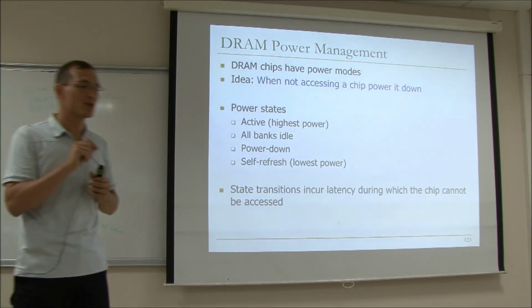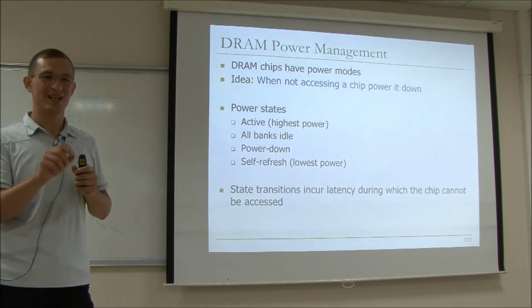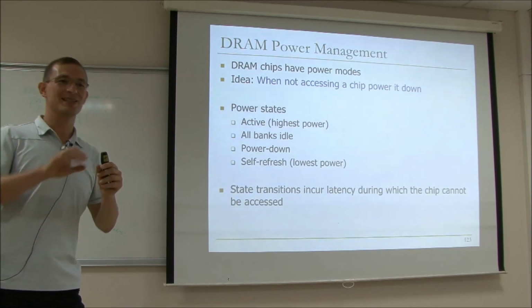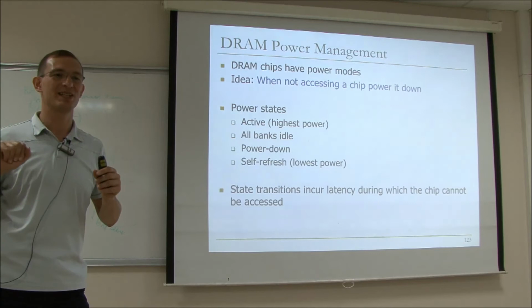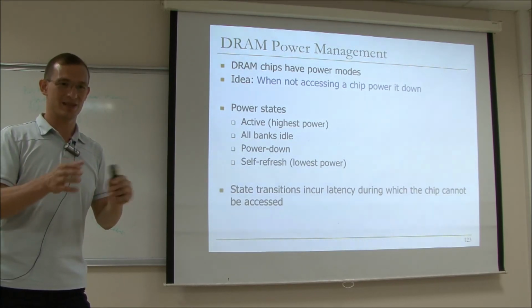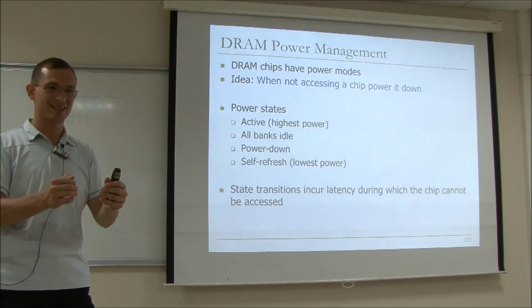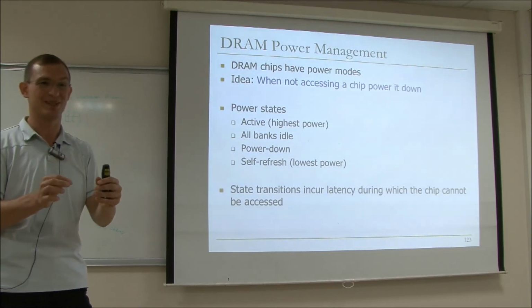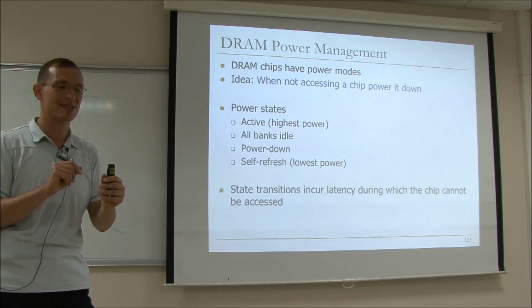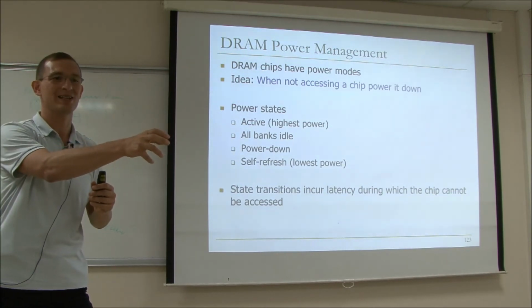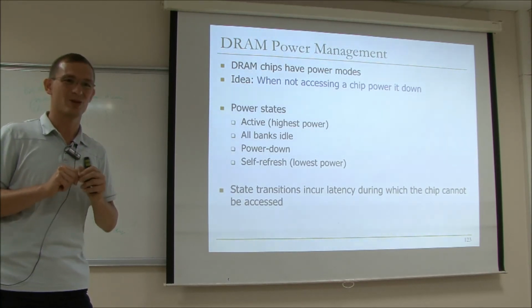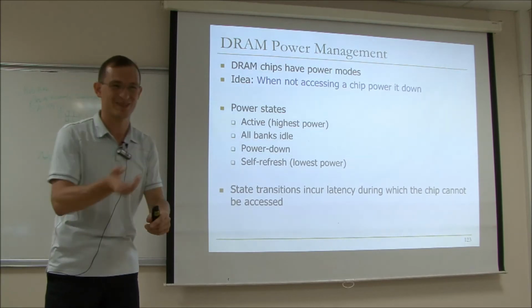So that's a good question. The row buffer is a cache, but it's also not fully a cache because you have to access it. Meaning you cannot take any data from DRAM without putting it into the row buffer, because it's also the sense amplifier. So it is a cache. Once you access it, the key question is, do you keep the data over there or not? So in that sense, it's a cache. But if you want to access something else from the same bank, you have to destroy that row buffer. So you don't have an option of bypassing the cache, for example.